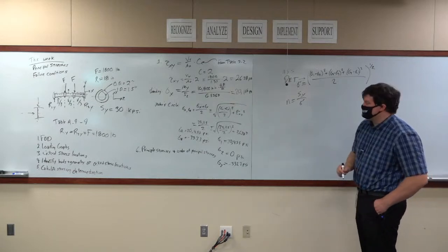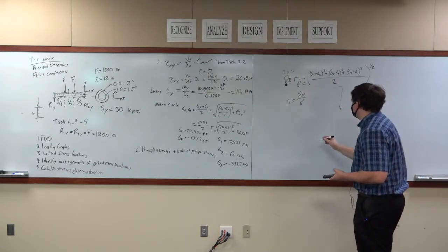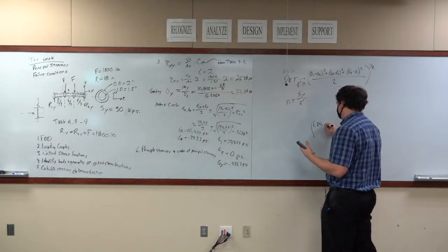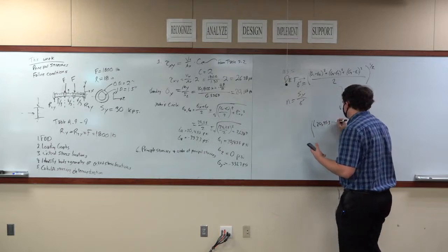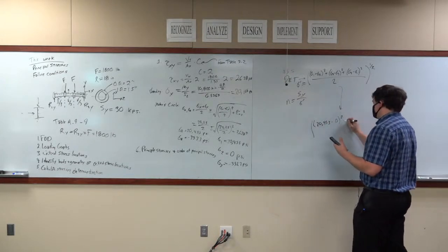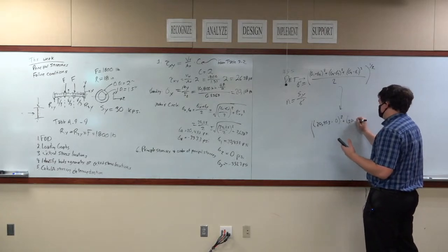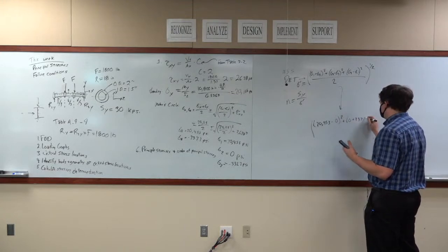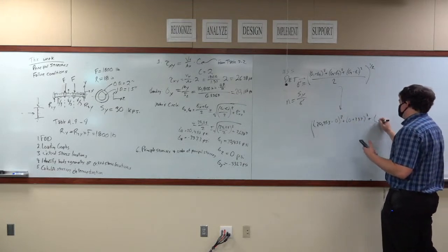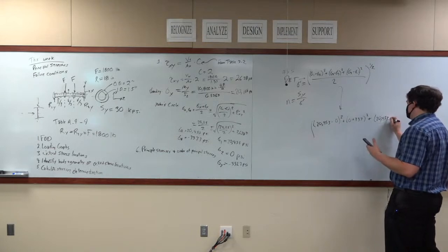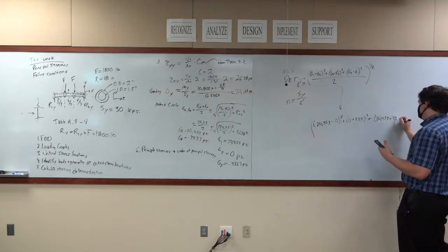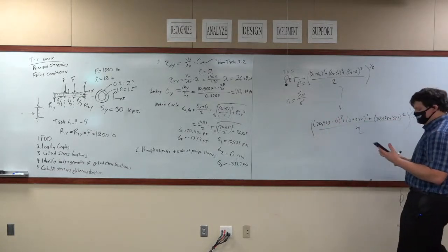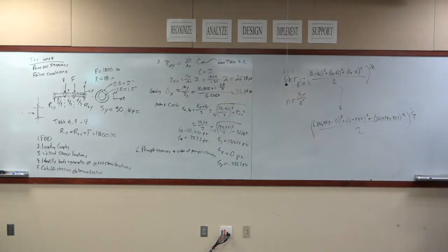I'm going to go ahead and plug this into my calculator real quick. The von Mises stress is 20,453 minus 0 squared plus 0 minus negative 337 squared plus 20,453 plus 337 squared, times 1/2, then the square root. This is fun math for your calculator.